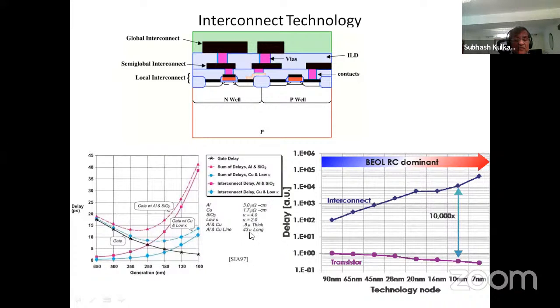These are some of the resistances and constants that are going with these materials. Aluminum and copper lines, they cut them down to about 43 micron long sections, not beyond that. So you don't run any copper line which is 100 microns. You make it say 40 kind of thing to limit your capacitance.